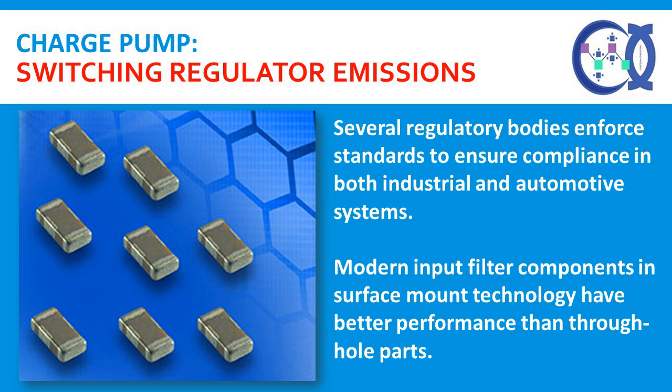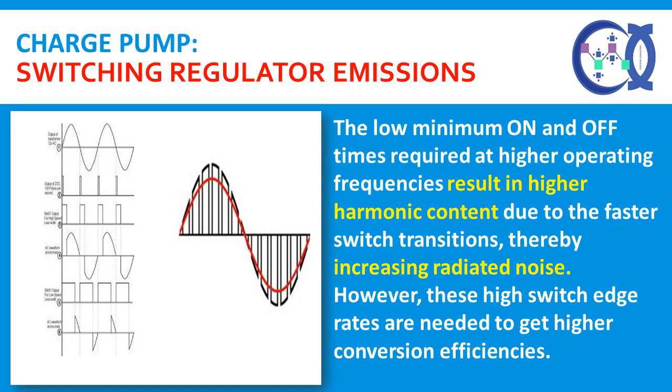Modern input filter components in surface mount technology have better performance than through-hole parts. The low minimum on and off times required at higher operating frequencies result in higher harmonic content due to the faster switch transitions, thereby increasing radiated noise. However, these high switch edge rates are needed to get higher conversion efficiencies.